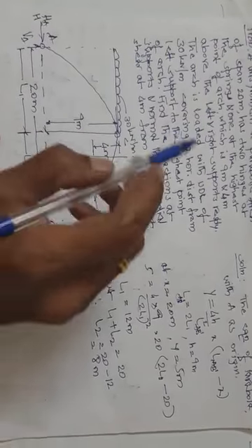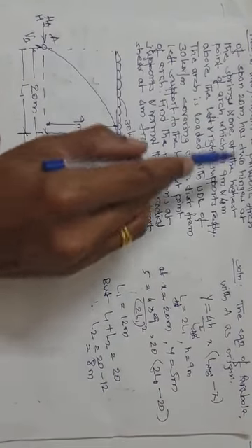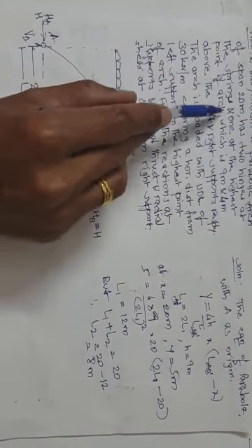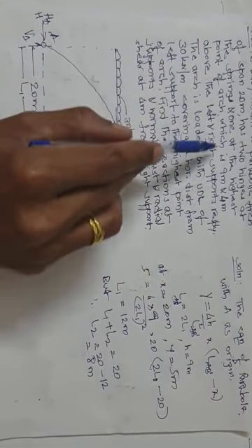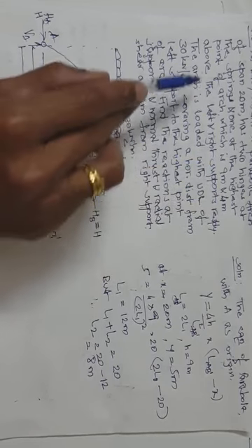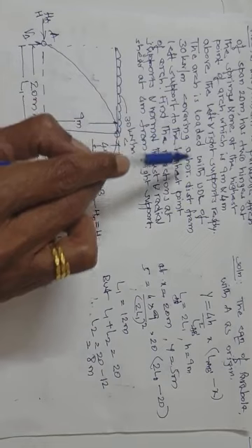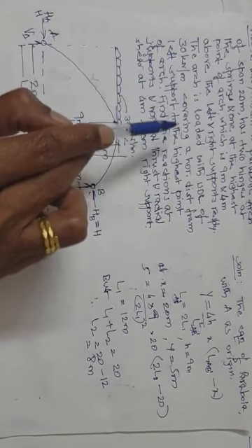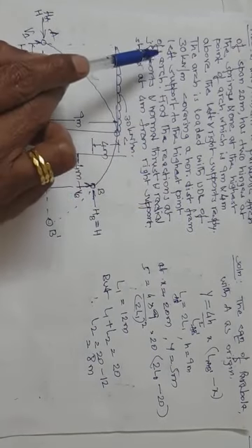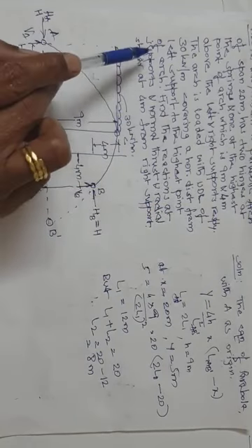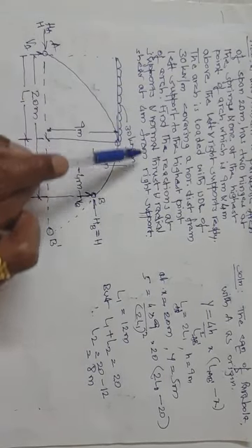Let us consider one unsymmetrical arch here. An unsymmetrical parabolic arch of span 20 meter has two hinges at the supports, one at the highest point of the arch, which is 9 meter and 4 meter above the left and right supports respectively. The arch is loaded with a UDL of 30 kN per meter, covering a horizontal distance from the left support to the highest point of the arch. Find the reactions at the supports and normal and radial shear at 4 meter from the right support.